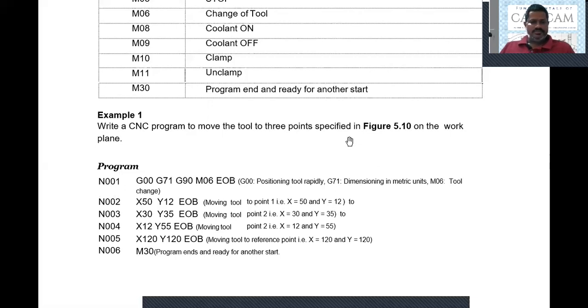Okay. So then, as you can see, you have G00. That means initially the tool is somewhere else. So we do not know where the tool is. In that case, we are going to move the tool rapidly, a rapid positioning of the tool. So we are rapidly positioning the tool to the 0, 0 coordinates, that means where we have the origin. Of course, in some cases, we are going to specify X00 and Z00 here. If we want, we can specify. And G00 along with X also we can specify.